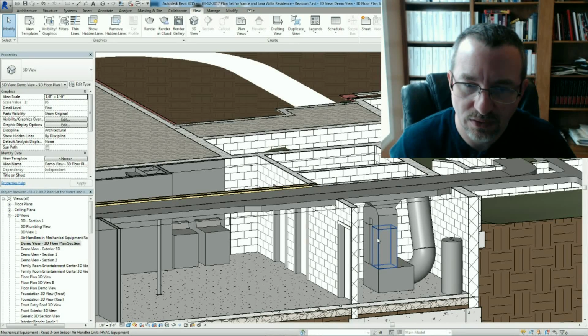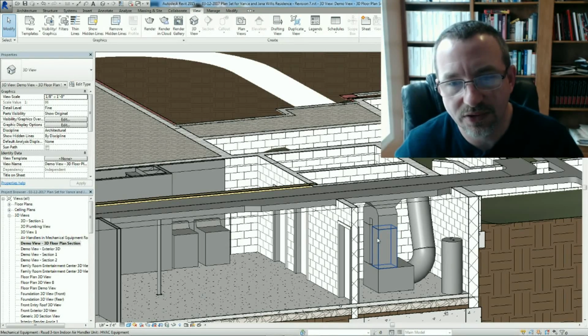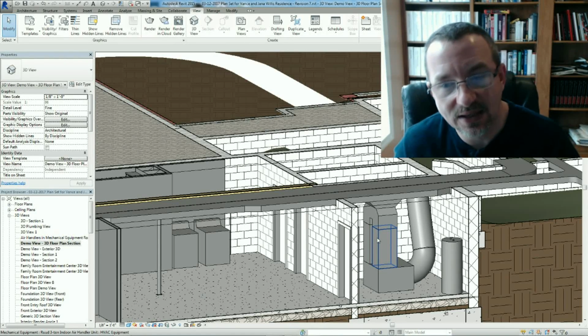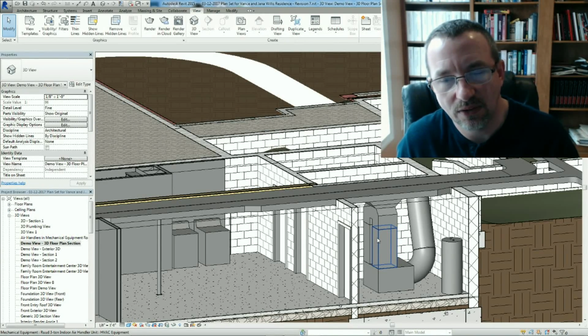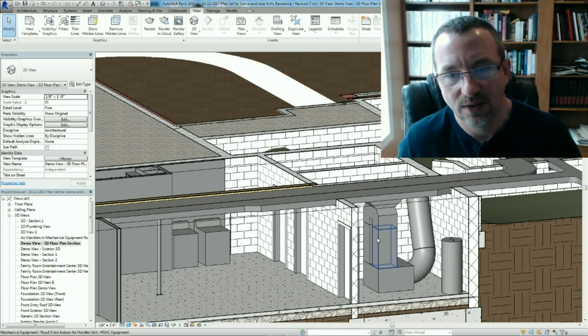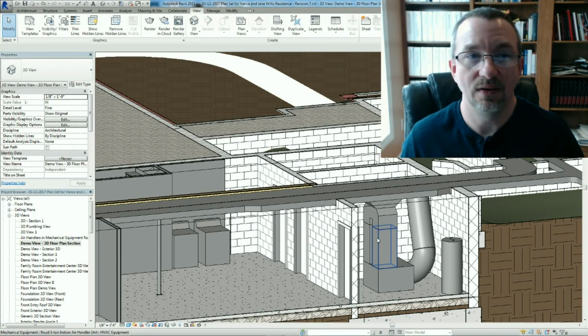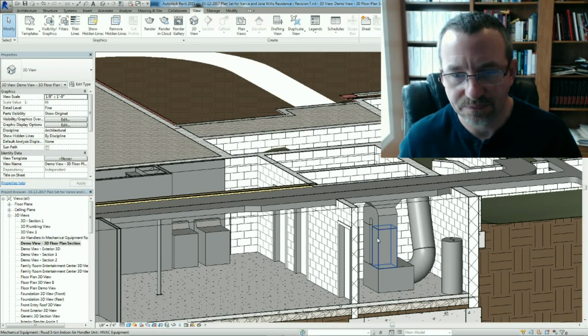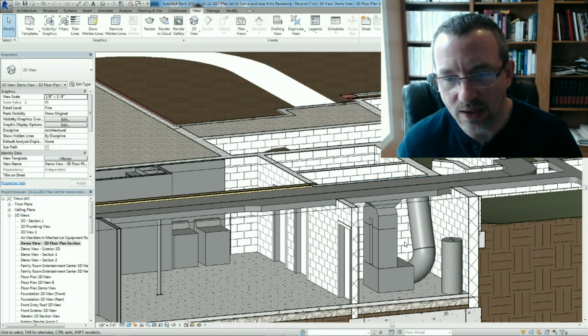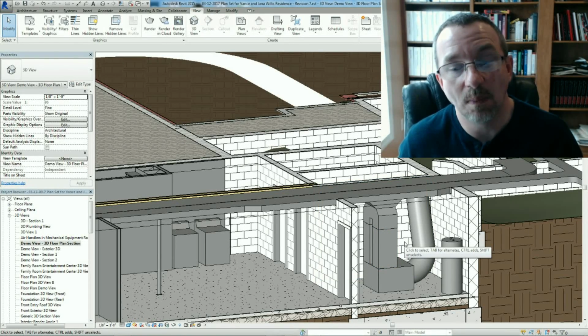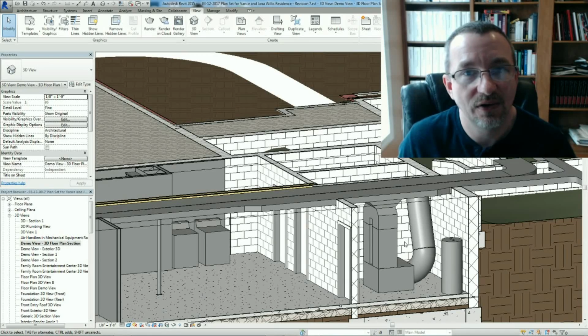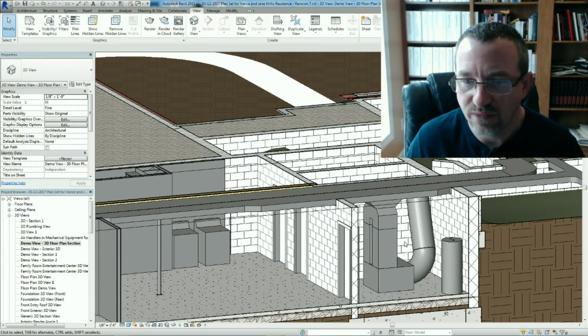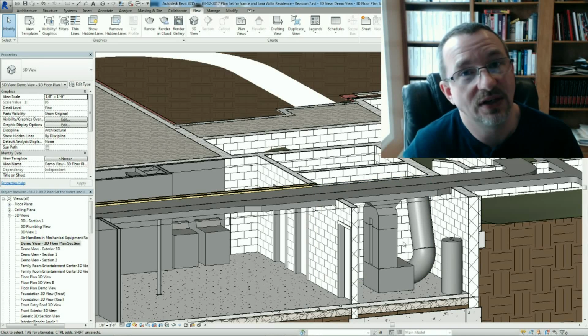So together they're 6 tons for my whole house, but they're staged, and my thermostat stages them. So the way it works is there's 2 stages of cooling, one unit on or the other unit on, and then there's 4 stages of heating. You know, one heat pump, the second heat pump, then the first electric heat, and then the second electric heat, the auxiliary heat. So there's 4 stages of heating. So for that to work, it actually requires that the air handler fans are both running all the time, because you have to have the full airflow to circulate the whole house, which both of those air handler fans are in parallel the way this works. So that's how that staging is done, and it works out great actually.